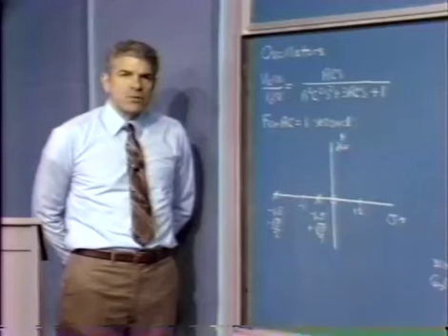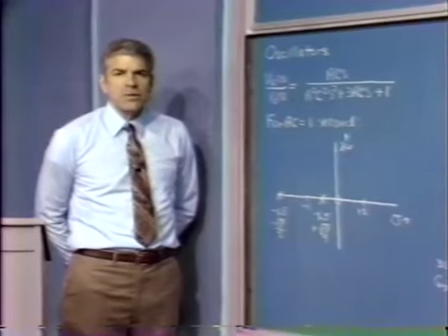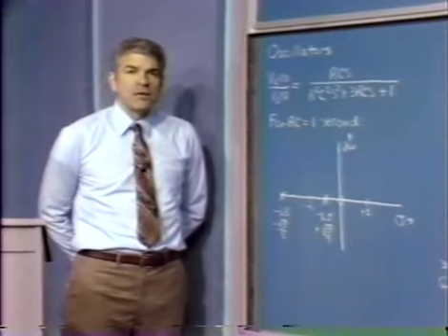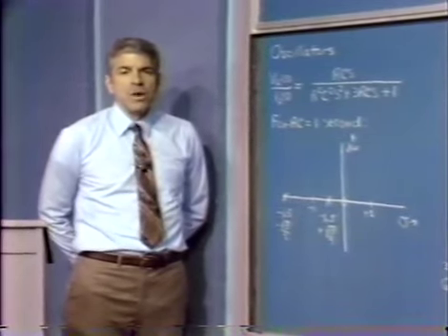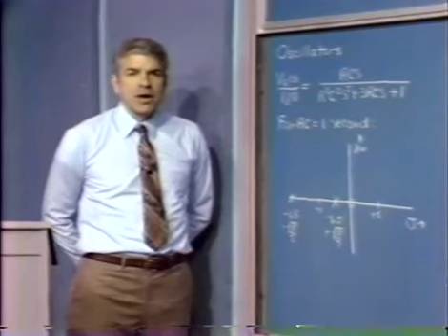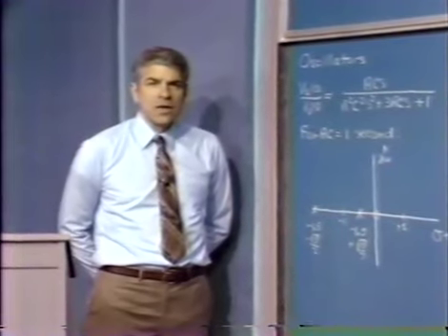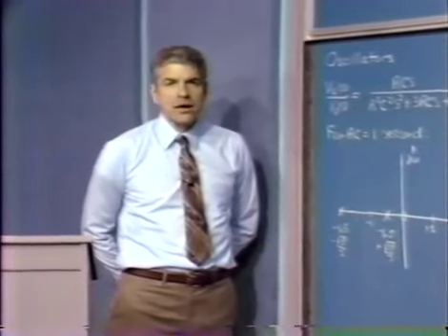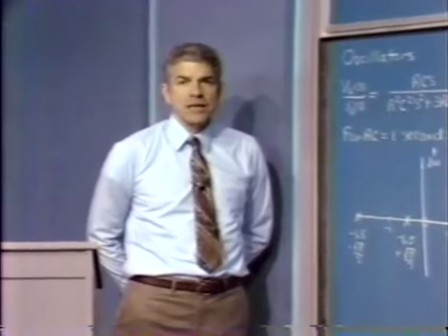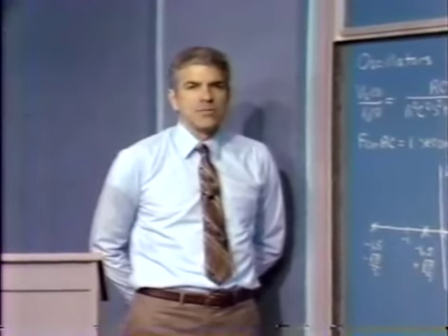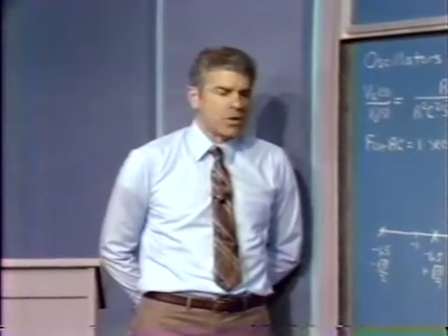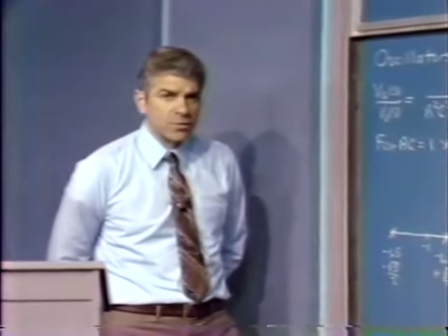We developed most of our root locus rules by arguing that in order to be at a point on the root locus, when we evaluated the angle of the AF product, that angle had to be an odd multiple of 180 degrees. In other words, the AF product had to be real and negative, with no imaginary part, in order to be at a point on the root locus diagram. That was necessary to cancel the inversion that in our standard topology we assume occurs at the summing point.